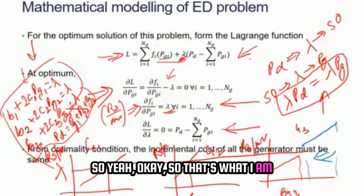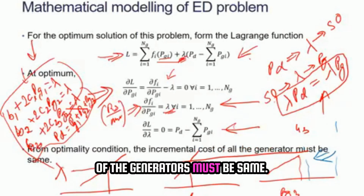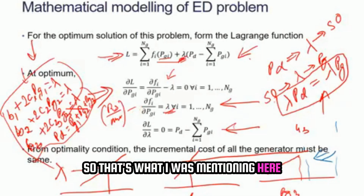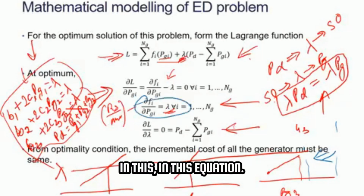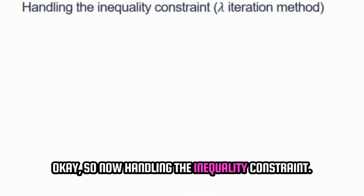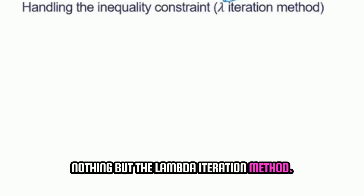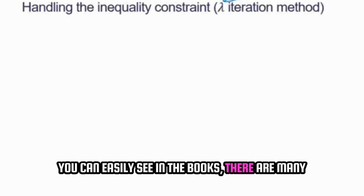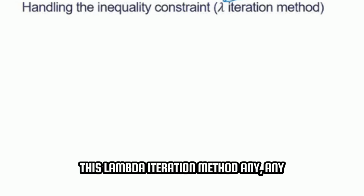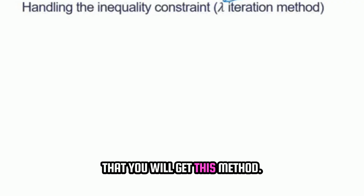Okay, so that's what I am mentioning here, that at the optimality condition all the incremental costs of the generators must be the same. So that's what I was mentioning in this equation: all the incremental costs of the generators must be the same. Okay, so now handling the inequality constraint. The method which I am telling you is nothing but the lambda iteration method. You can easily see in the books, in all the books you will find this lambda iteration method. Any power system book you take as a reference, there you will get this method.